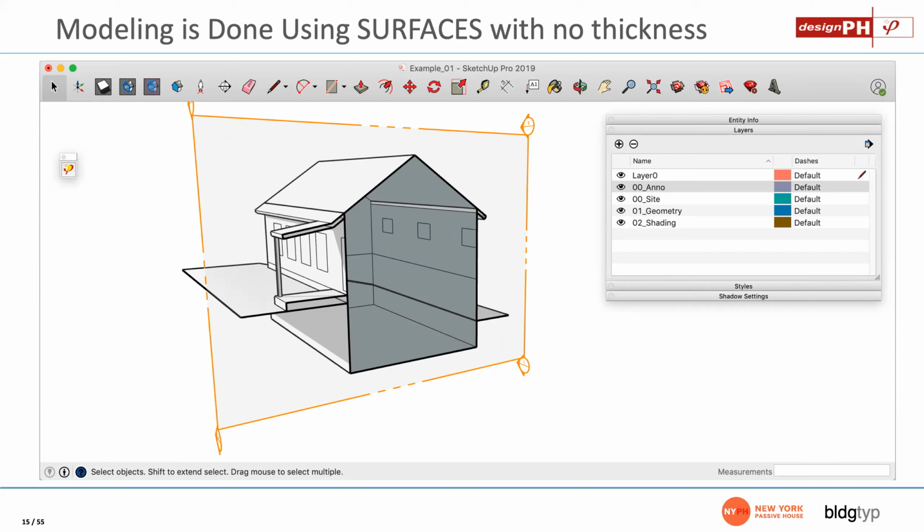So often quite a bit different than your architectural model. You can either pull this information out of a complete architectural model, or maybe you rebuild it from CAD drawings. Lots of ways it can be done. But in any event, you have to have a completed, simplified planar energy model in order to interface with the PHPP properly. So we're going to build a no-thickness, flat planar model.